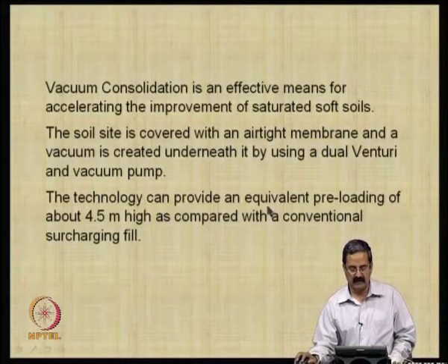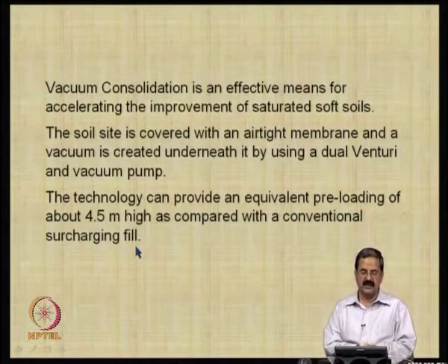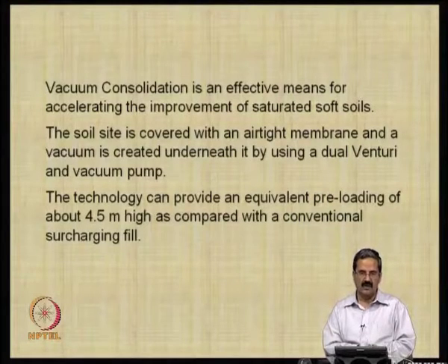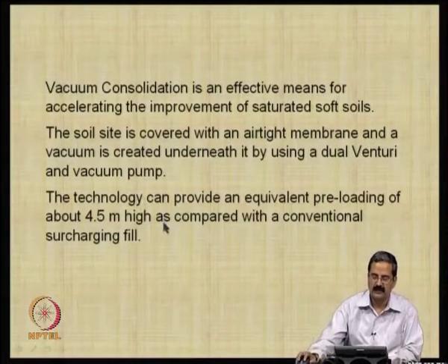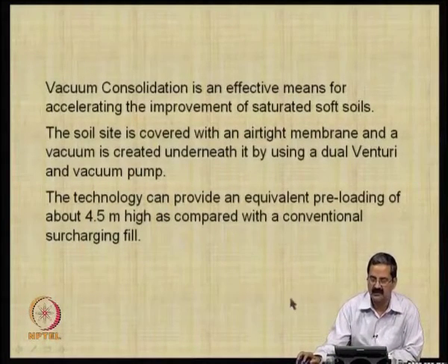The technology can provide an equivalent preloading of 4.5 meters high, compared to conventional surcharging fill. So instead of 4.5 meters of sandbags or whatever surcharge, if you apply this vacuum properly, one can get a very good effect.